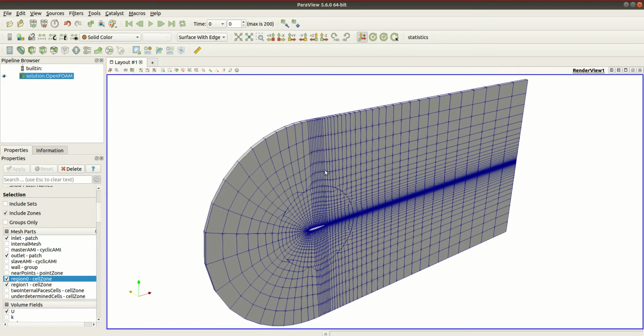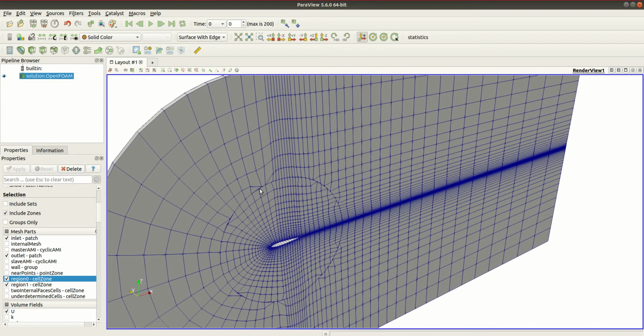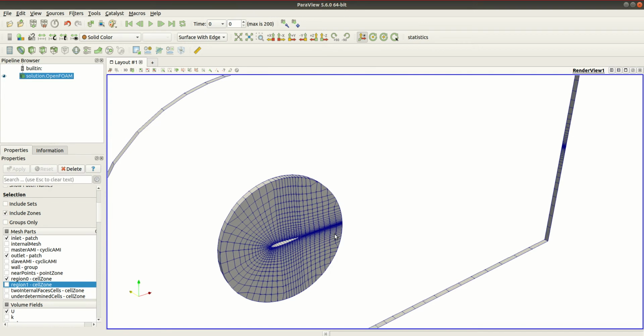Here we will basically split the mesh of the airfoil in two regions with an axisymmetric geometry, which is a sphere or a cylinder. In our case, we'll use a cylinder because the case is 2D. So we will define two regions in the mesh: region 1, this circular region where the airfoil is enclosed, and the external region, which is the base mesh that we used in the previous cases, minus this region 1, let's say.